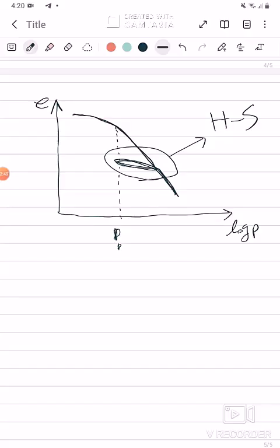From another point of view, we can say that if deformation is important for us, the HS model is preferred to the Mohr-Coulomb model, because in deformation, the stiffness parameter has a key role, and this is the key factor, and the stiffness parameter is considered more appropriately in the hardening soil model.